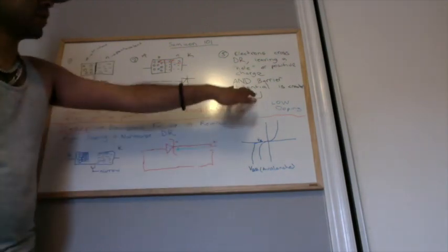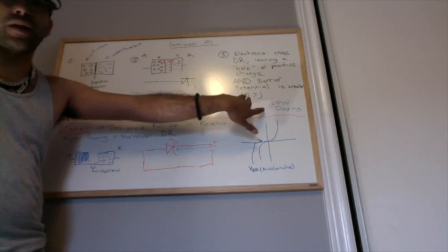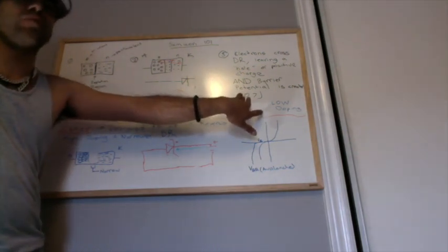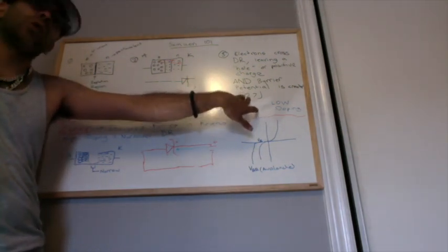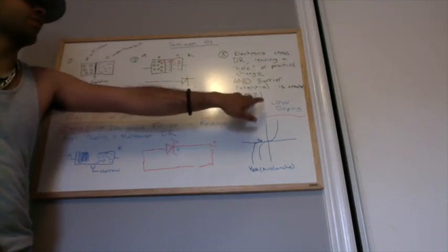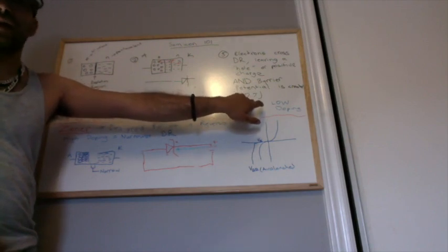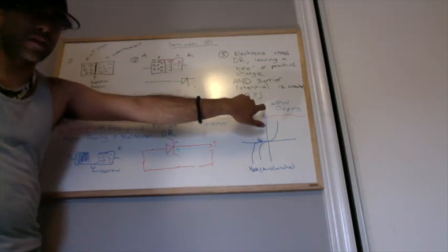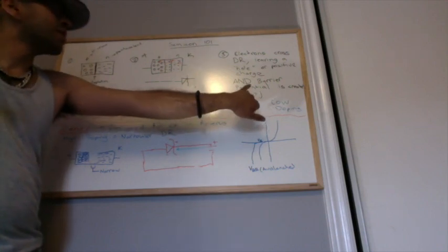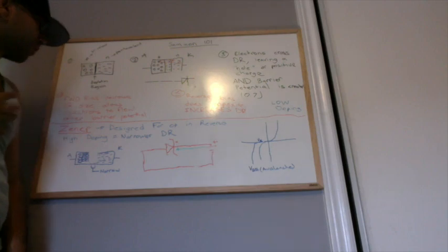In silicon, the barrier potential, that's why you'll get 0.7 on all these labs, or somewhere very close to it, depending on instrumentation error or just a bad diode or whatever. 0.7 is the barrier potential for silicon diodes. Anything silicon, really, even transistors, and that's going to be the next video. And 0.3 for germanium, but I left it off this board.